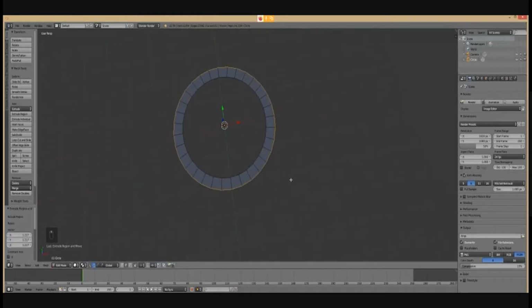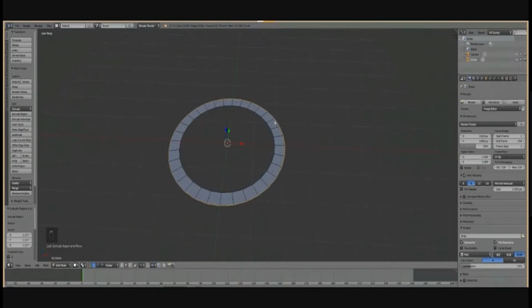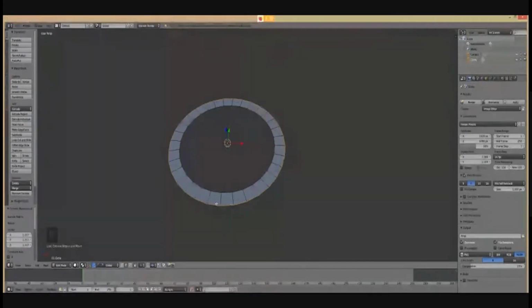Okay. If I wanted to view the top view of this, I can press 7 and I'm automatically in the top view. If I wanted the side view, I can press 1 or 3, right? So that's fine. Now that I have this, I want to extrude this entire surface up. And to do that, right now, if you notice, it is an edge select. I can choose face select, and now I can select the different faces, right?